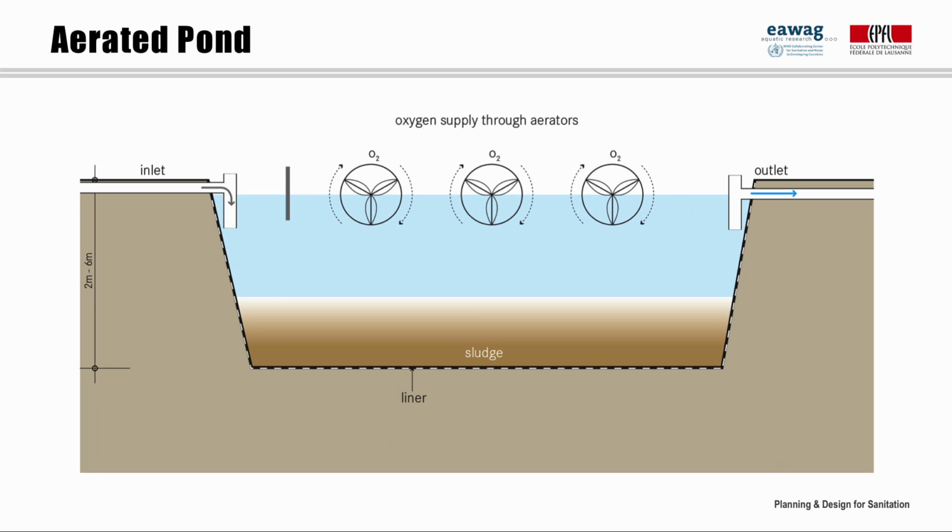of organic degradation. Increased mixing and aeration means that the ponds can be deeper and tolerate much higher organic loads than a maturation pond. The depth may be from 2 to 5 meters and the retention time from 3 to 20 days. In some cases, it can even replace the anaerobic pond, thus avoiding the bad odors that anaerobic ponds may generate. The downside of it is that aeration implies a high energy consumption and thus costs and requires a constant source of electricity. Interruption of electricity service may cause the pond to turn anaerobic, thus changing completely the inner biological processes.